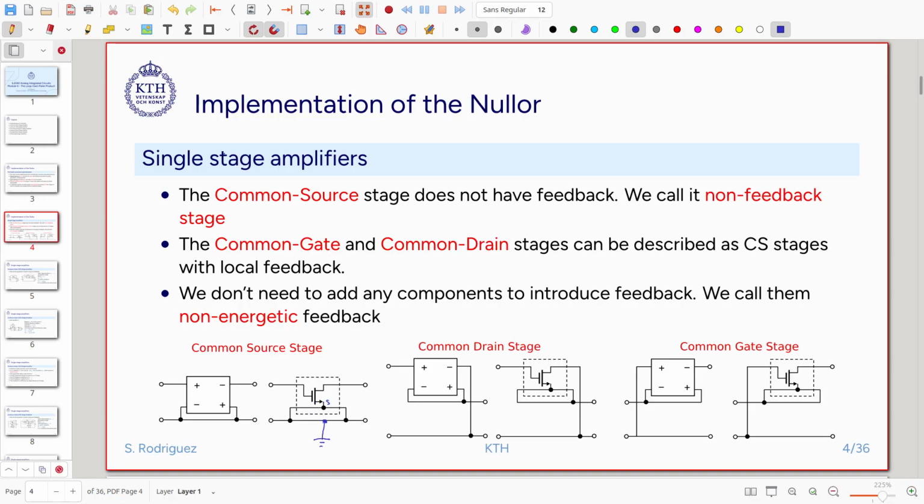And then we have here the two-port model for this amplifier. If we consider that it is an ideal amplifier, the two-port model will be like this. We have one terminal that is common at the input and at the output. That will be the ground terminal. We already studied a little bit about this, the intrinsic gain characteristics, the ABCD parameters, and the position of the poles of this configuration. Now we are going to study the common gate and common drain configurations.